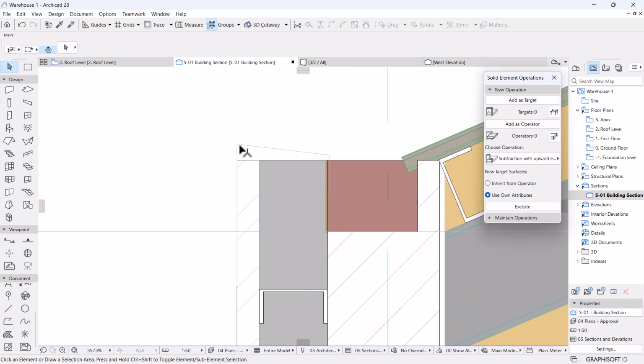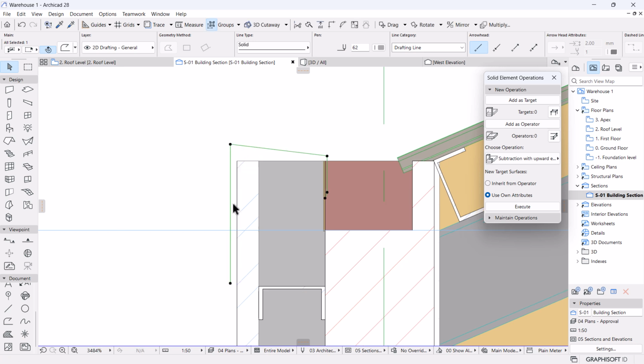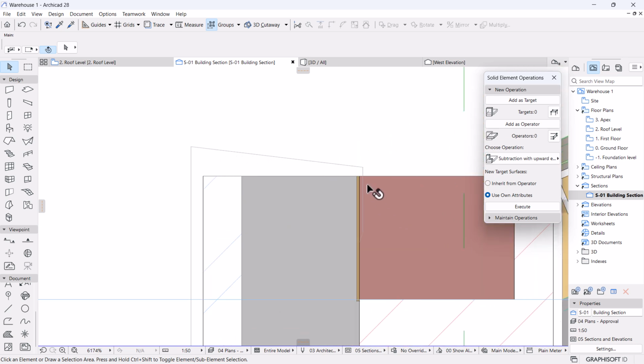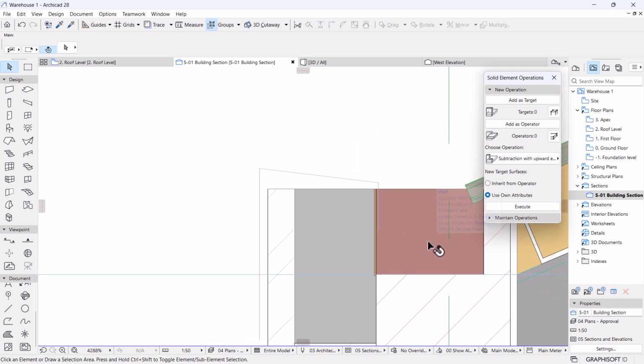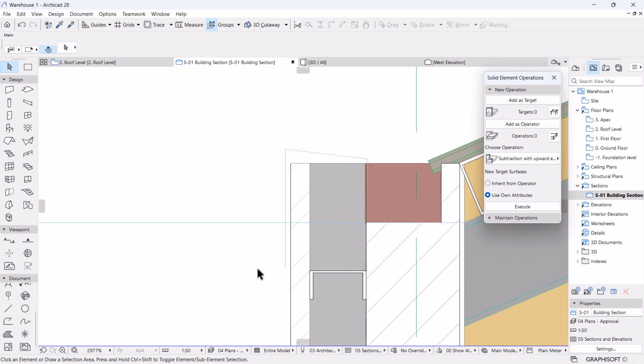There should be a flashing like this around the cladding and then the gutter, and it has to be sloping either way. If that is slope, it slopes within the gutter to direct water or to promote fall of the water, or it slopes on the outside of your building.